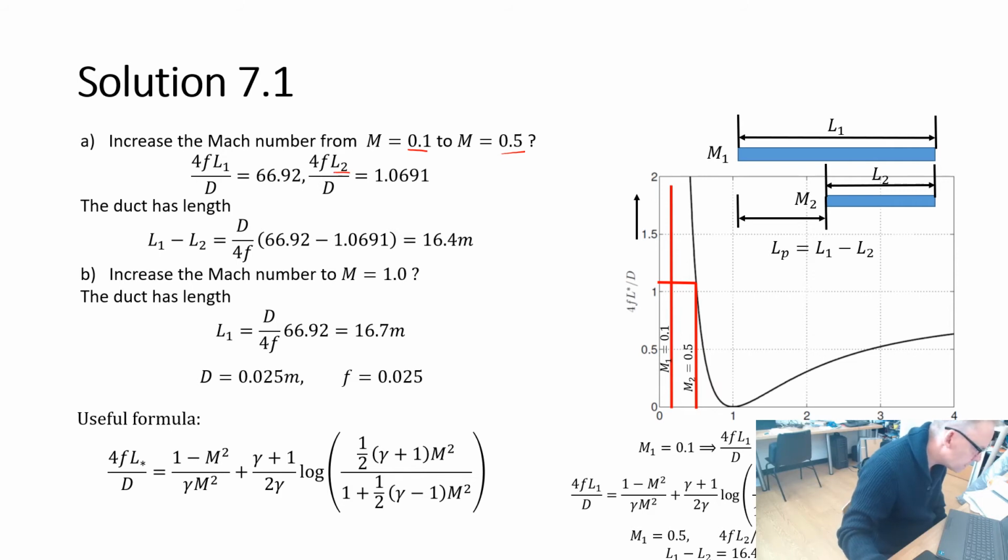we can determine the critical length it takes for the pipe to reach the sonic state. So we start off with Mach number 1. L1 is the distance it takes for the Mach number to become unity, and obviously if we have Mach number 2, L2 is the distance for that to become sonic as well. So we calculate those dimensions. I have to use the formula because, as we see here, as the Mach number tends to 0, the length has a logarithmic dependence on the Mach number.